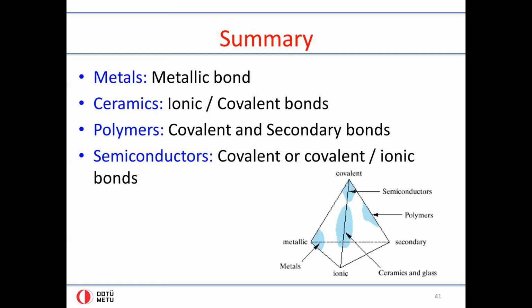This doesn't mean that they completely disintegrate, because the covalent bonds are strong, but the secondary bonds that hold together the chains of carbon that I showed a few slides ago will give and will separate the chains from each other, and you will have melting of polymers or burning of polymers if you try to subject them to high temperature.